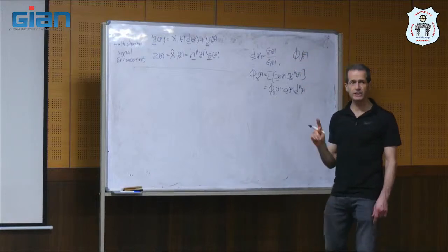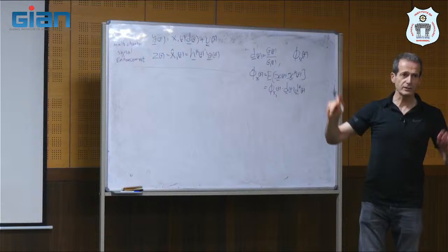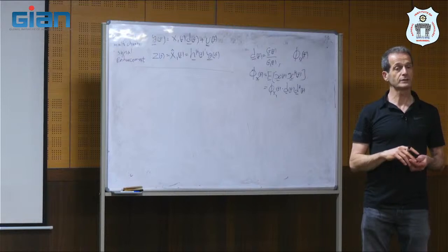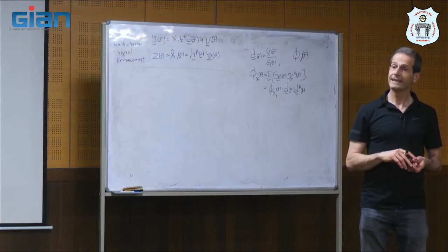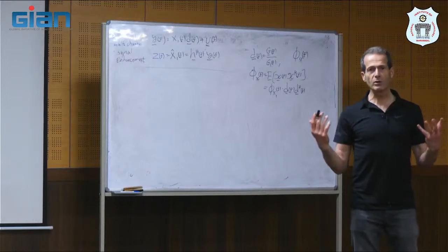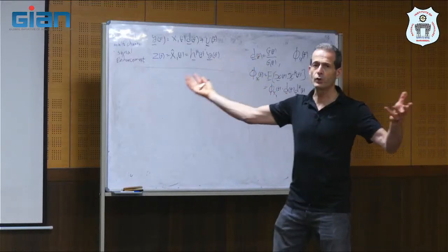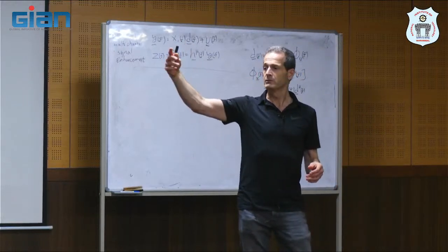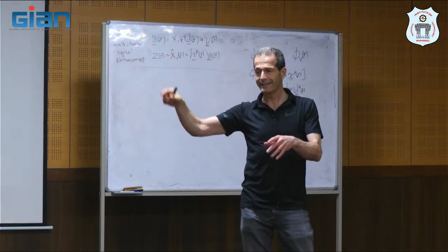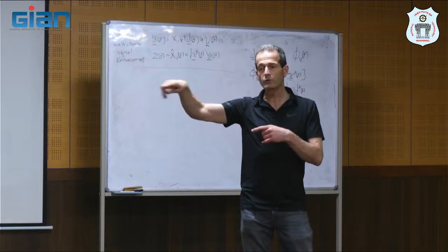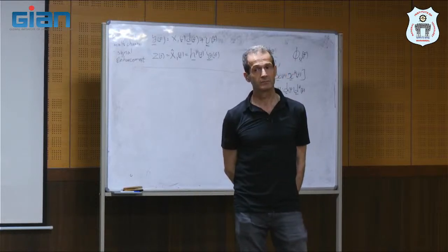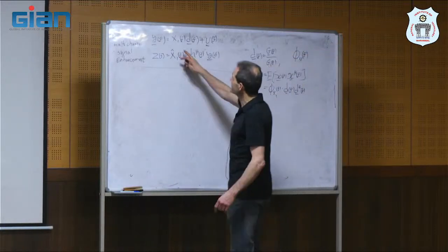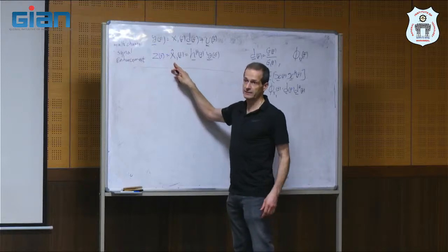So I know the correlation of the noise components between any pair of two sensors, which means that I know the environment, the background noise in the environment. Using the sensor array, I know how they correlate between two sensors. This enabled me to obtain an estimate of the desired signal in the reference sensor.